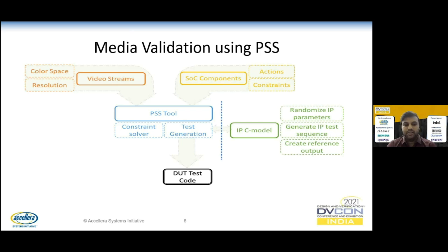So running individual test content, individual functionality of a media, would not be a major problem for us, because it has its own media DMA address location space where it will do the transfer, and where we inject or backdoor load the content before we do the processing. But when we do encoding and decoding in parallel, we have multiple instances trying to do a media transfer, encoding or decoding together. We end up with a DMA address overlapping issue.